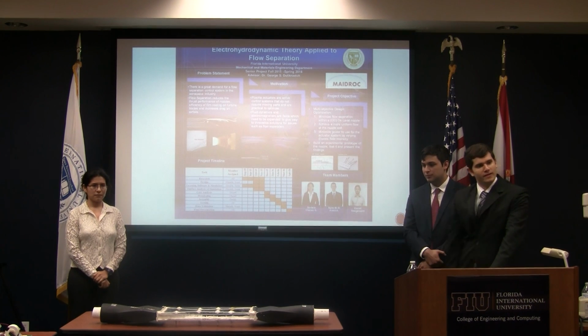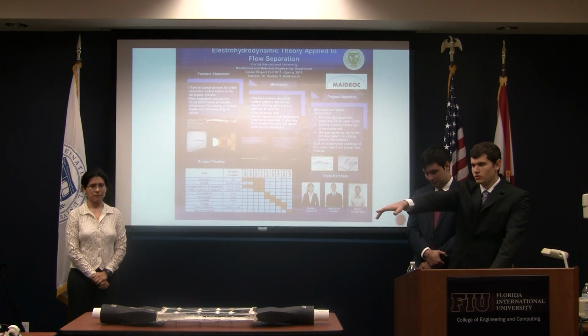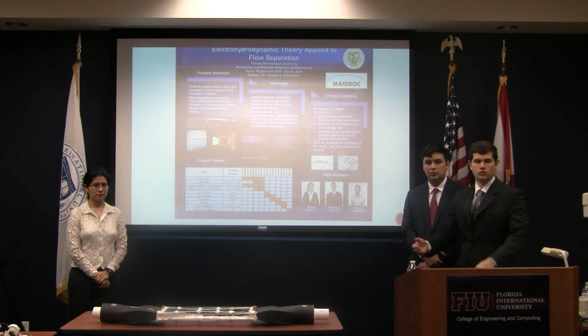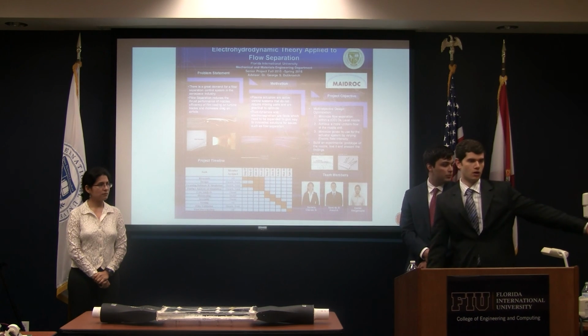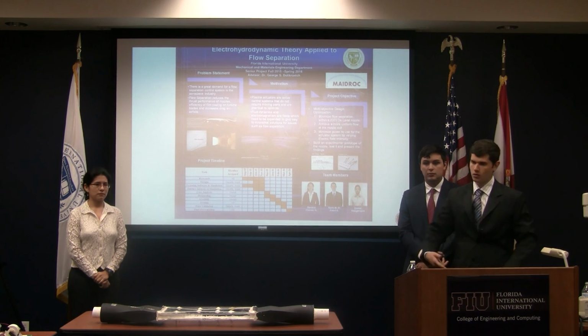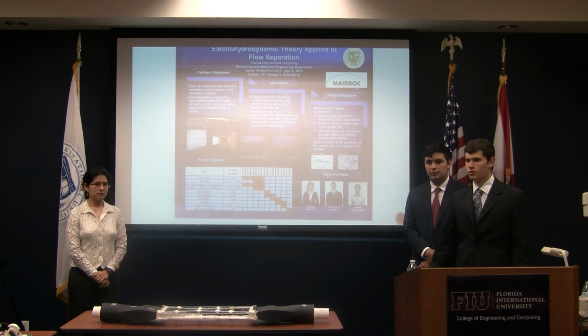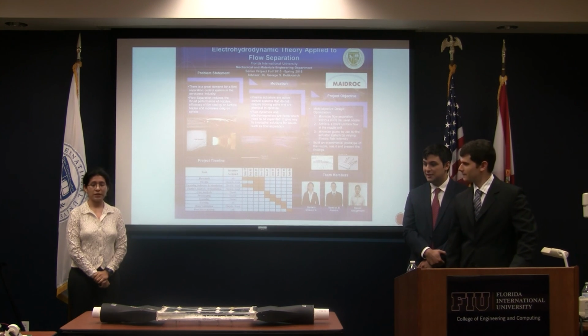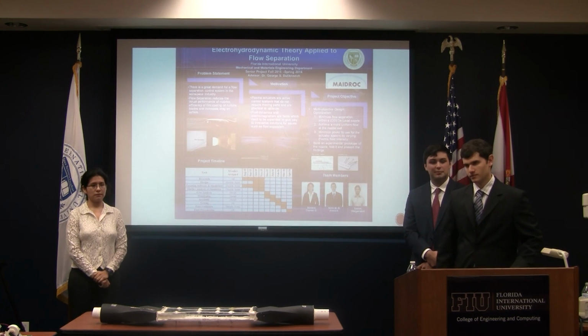Because I'm seeing that and I'm like, that must have been the biggest challenge. The first step we took into actually building that power supply is just trying to increase our voltage, turning it from AC, which is a 120 volt AC outlet, converting to DC and actually boosting it with a voltage tripler, or Cockcroft voltage tripler, theoretically. I was looking at that and said, oh, that must have thrown you guys for a loop. Yeah, we learned how to do it from scratch. Okay, just curious.